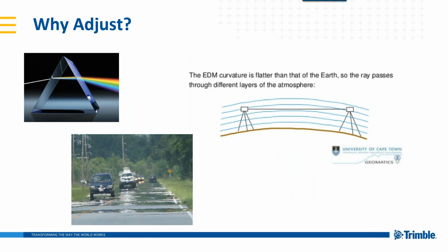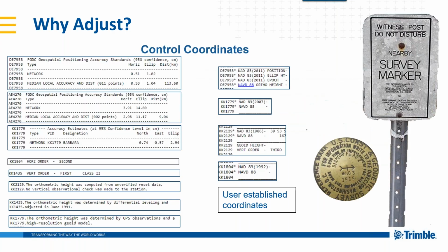On top of our instruments and our equipment that we're using, we have environmental conditions that we have to deal with. We've all seen the effects of refraction and the curvature of the Earth. So the temperature should be recorded properly. You may not think it makes too big a difference, but recording the proper temperature for each instrument setup should be carefully maintained or entered.